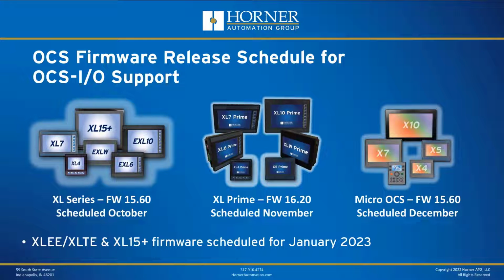Absolutely. You said it well. What it all comes down to with load cell and strain gauge applications is speed and resolution. And if you need really fast or really high resolution, then you're usually going to be better off with a specialty piece of electronics to deal with that. But if you're talking a routine weigh scale type application without super high resolution or super high speed requirements, then that millivolt input could be fine.